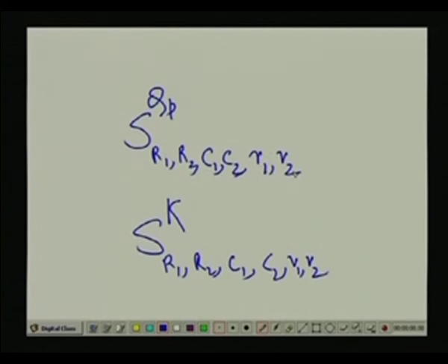Once I talk about that, you see in the case of your unity gain amplifier design, some of the sensitivities are 0. You will find that some of the sensitivities, especially the QP sensitivities, for the unity gain amplifier design are 0 for some of the elements, not for all the elements, right. So, this way you will find the sensitivities.